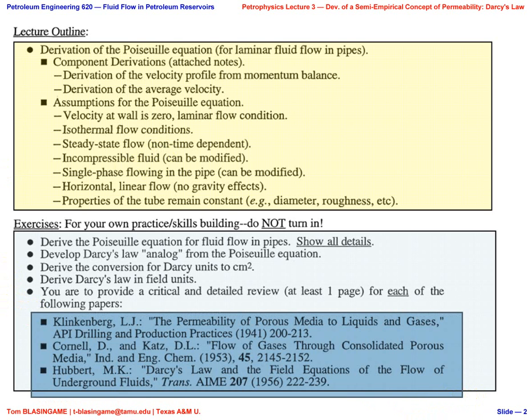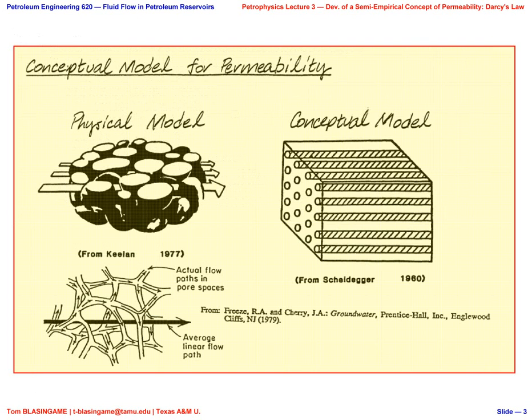Hubbard's equation is in the corresponding original notes lecture for this, which is in a separate folder, of course. This is the one where he tries to derive Darcy's law from Navier-Stokes theory, and he ends up having to make an assumption of permeability being, like I said, a direct geometric function of porosity. I mentioned that the other night.